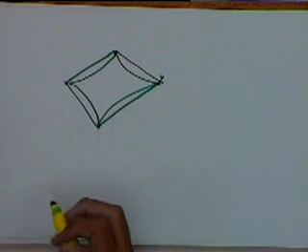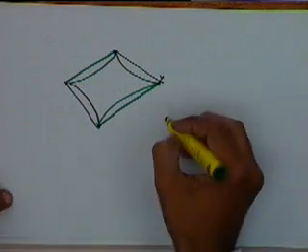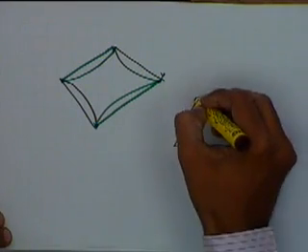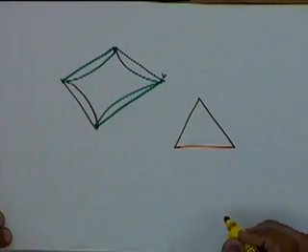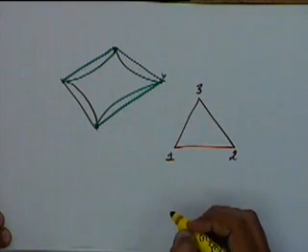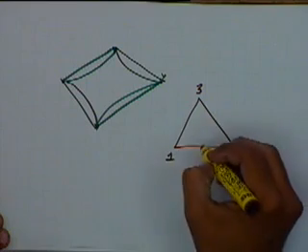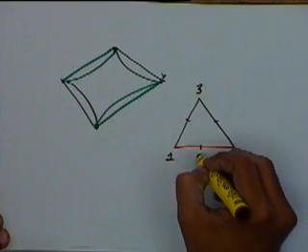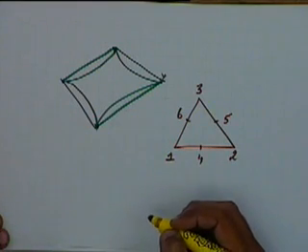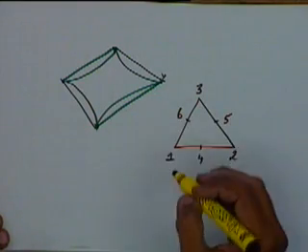Okay. Similarly, we have seen a triangular element, and we have defined a triangular element with 1, 2 and 3 nodes. We can also define a 6 noded triangular element, and again we can define 6 shape functions for that.